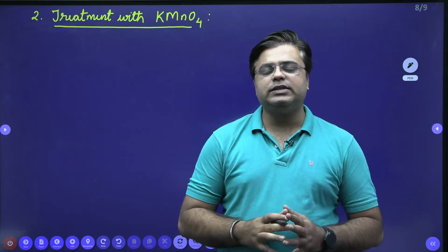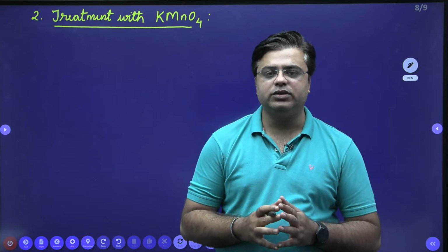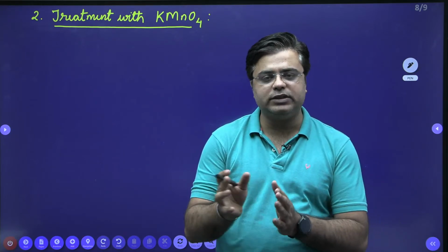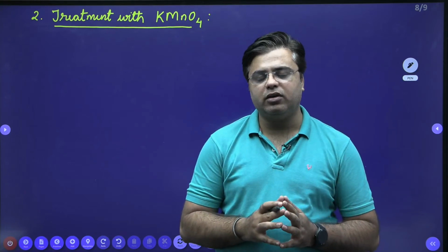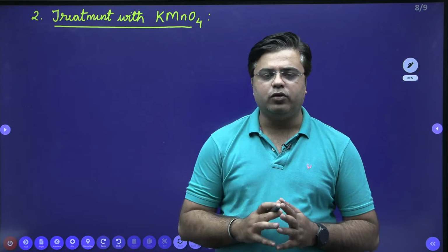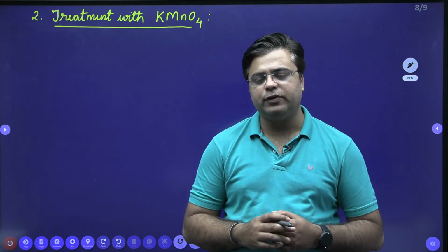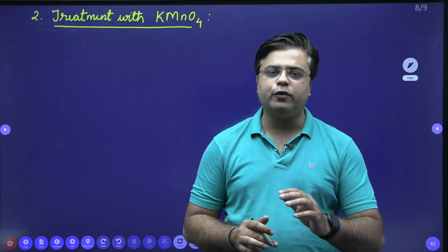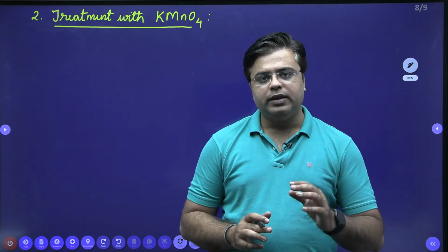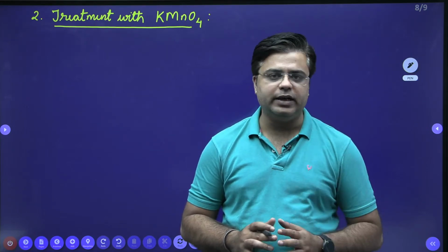Where wells are the only source of water. So the village people, or people from small communities who depend on underground sources from wells, add KMnO4. KMnO4 is a pink substance. They add KMnO4 for disinfection and leave this water for 48 hours. Okay. They add KMnO4 in the wells and leave this water for 48 hours.